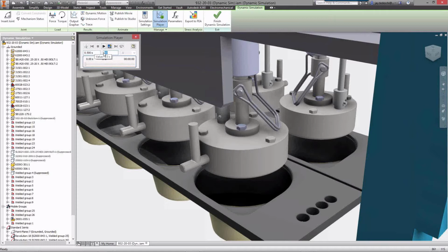So you always need to keep in mind when you're setting up your simulation, and I hate to use the term level of detail, but that's exactly what we're talking about here, how fine or how coarse an event is. So that being said, we're going to set that to 50. So we're going to get 50 time steps or 50 iterations generated in that half second.